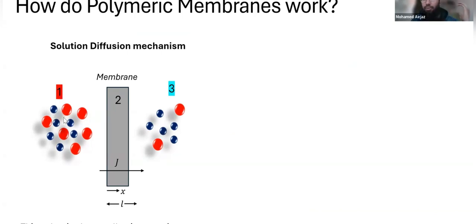So you would pass this, usually called the feed side, your gas feed, through the membrane. Initially it dissolves at the membrane side, and in step 2 it diffuses through your membrane along the direction of your interest. The membrane has a particular length, and the diffusion is directly related to the thickness and the direction that you're looking at. At the end you have the effusion of your gas molecules, so you have the blue separated from the red, and then you're happy, right?